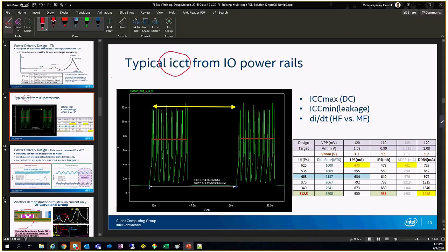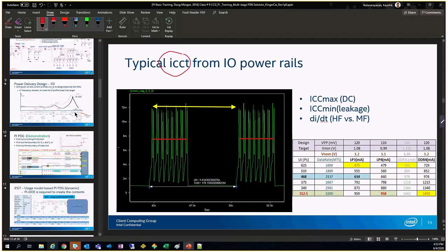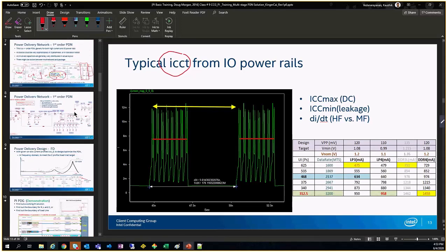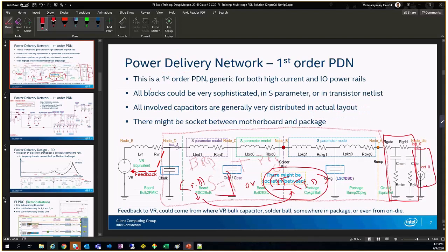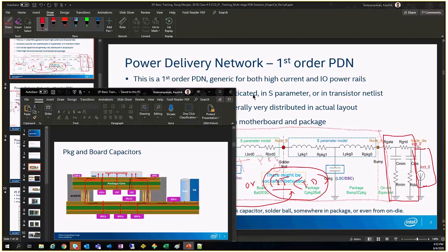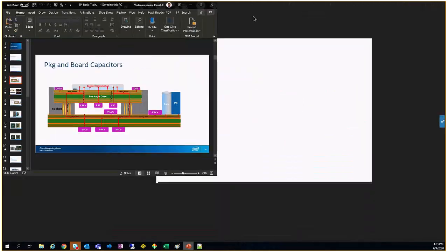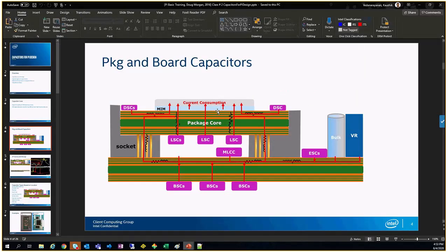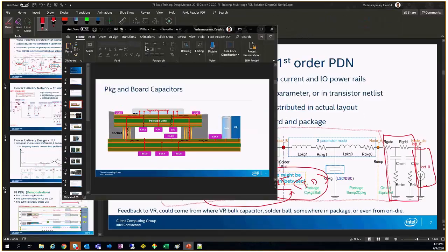He will look at the operation, and in his tool he will see, at the bump at this part of the PDN network, right over here, what is the current seen there. He will run a full-fledged operation in his circuit simulator tool and see how the current varies at this location. He will probe and check here, and he will give that current to us, which will look something like this.